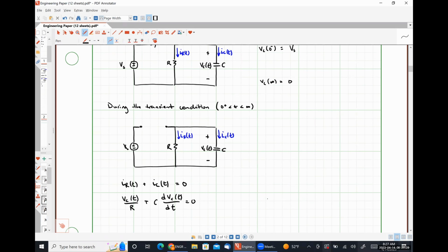And we once again have a homogeneous first order differential equation, which, based on our experience from 5 minutes ago, a very educated guess for the shape of the capacitor voltage response would be Ae to the st as well.